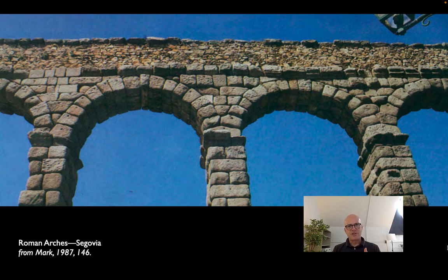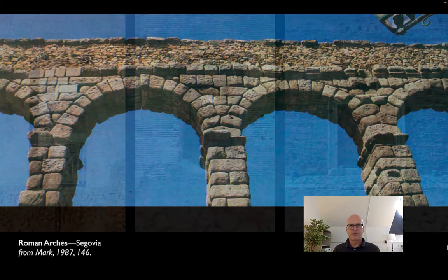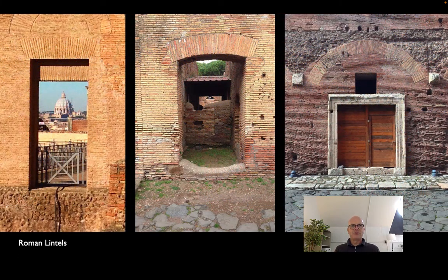And you can see that the arches sit on what looks like a sort of rudimentary column capital. And in fact, we think that is where the scaffolding for the arches probably sat. And I'll talk about that in a little bit, why the semicircular shape is one that we see again and again in Roman construction, and why in this case those little ledges are actually super important. So that's a simple semicircular arch in stone. And the advantage of brick is that you can fine-tune the shape of the arch to whatever situation you have to hand.